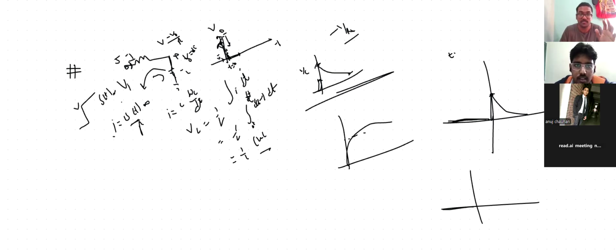When it is trying to charge or discharge, it will charge fully, meaning the full amount of energy is gone earlier in the impulse response. Now it also tries to go fully, but here some voltage is there, so the difference will be very less, right? So it will charge slowly. This slow rate is because of the resistor, which stops the current. When the cap fully charges, it will develop some voltage from 0 to 5 volt. When the 5 volt came, the difference is 0, then it will stop charging.